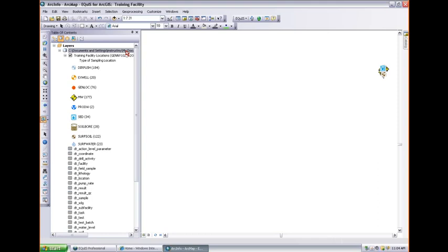There's ArcSDE geodatabase, that's the enterprise one. I saw that you guys have some ArcSDE layers, but we currently don't support writing your output work into ArcSDE. If you want to put this output into ArcSDE, we can create a geoprocessing model that copies that over every Friday after work or something, if you want to store all of these output queries in one place, so that you aren't reinventing the wheel. If someone's already created pie charts or TCE layers, you can use the search tool, the same one I searched for Bing with, to search your internal repository for the layers. And with the metadata, you can see exactly what and when they created that layer.